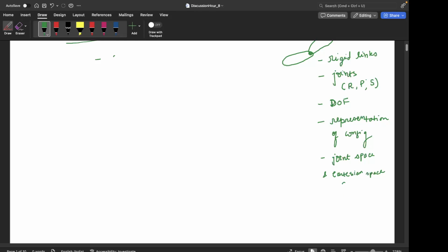That is given in the SE(3) space, the special Euclidean group, which is the homogeneous transformations that we discussed: the 3 by 3 rotation matrix, the 3 by 1 translational part, and here zeros, and 1 is the scaling factor. This representation combines the entire information in a very condensed form, and can be used to describe the relationship between one frame and another frame, right?